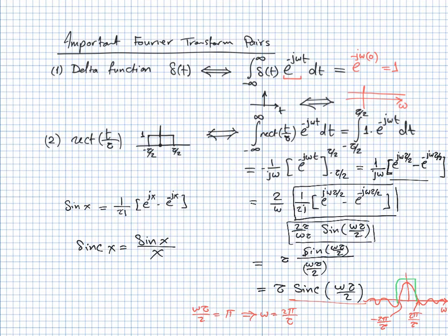So I can practically ignore all the others and say that typically it occupies in frequency this range, from minus 2 pi over tau up to 2 pi over tau. And that's going to be the practical bandwidth of this signal. This is how much it occupies in the frequency domain practically. The remaining ones are very small and I can ignore them. Assume that it gets there and then just disappears. Even though it stays, this is going to cause a very small error in my calculations. It's not a big deal. So that's why I really care about where it first meets 0. That's why I made the extra effort to find these points.